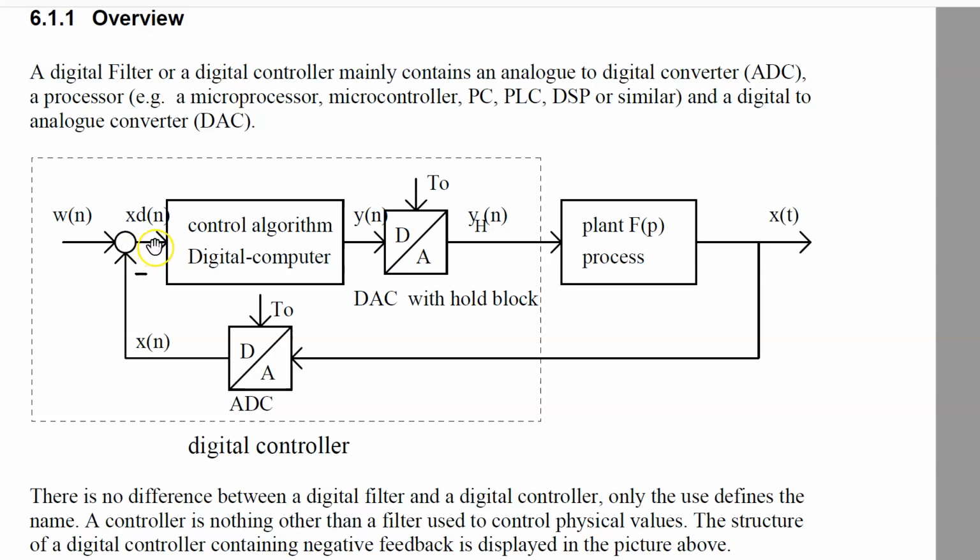This goes into the algorithm, and the algorithm calculates a control output value, which then is sent to the actuator input of your process. So the process includes sensor at the output and actuator at the input, and process behavior in the internal block here. So this block is the complete system, including sensor and actuator.